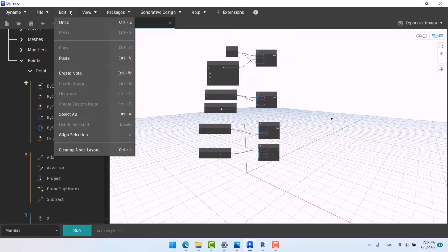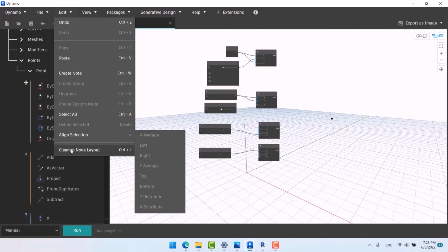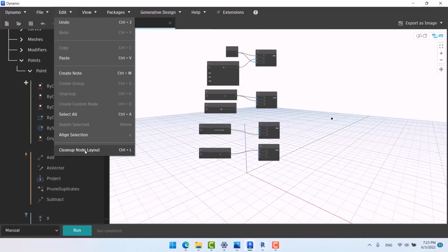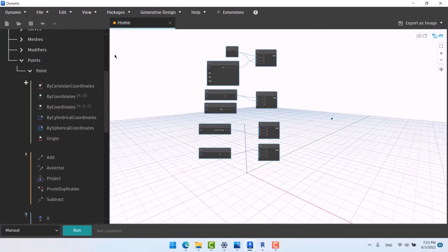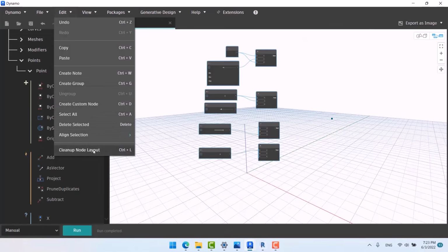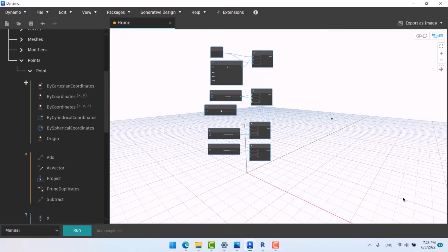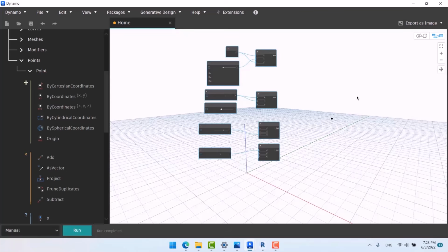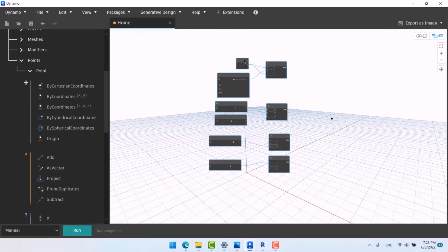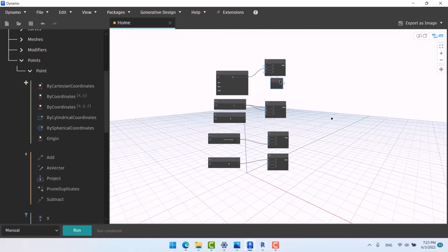Well, we were saying that in the edit tab, we have line selection and cleanup. What do they do? Cleanup is not in our control. It removes the free spaces as far as it knows fit. For example, if I draw a frame here, then if I click on cleanup, it makes them be close to each other, a little bit more compact. It often disassembles the node's rhythm. In fact, I don't agree with it. Well, for example, it puts it here, like between these two. Actually, I want it to be here, and I want to maintain the rhythm and the reading of my nodes.